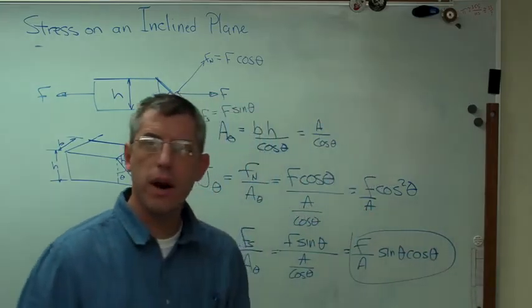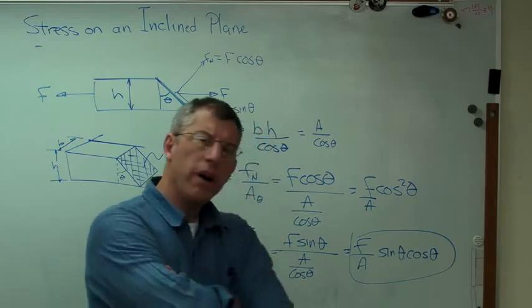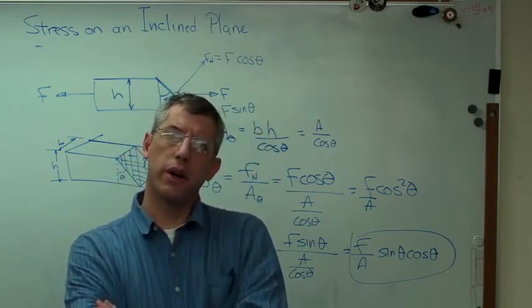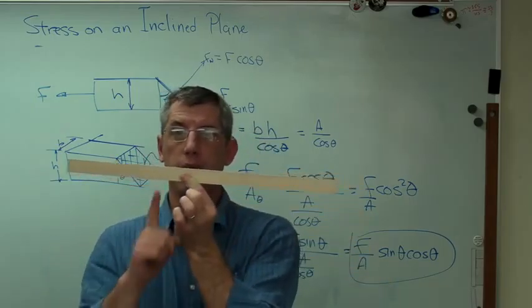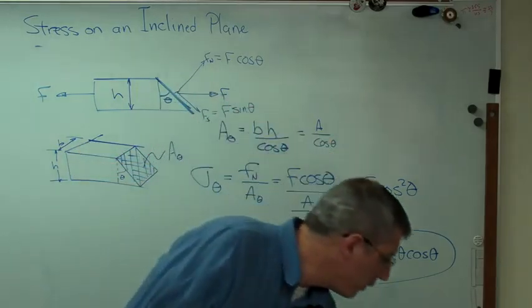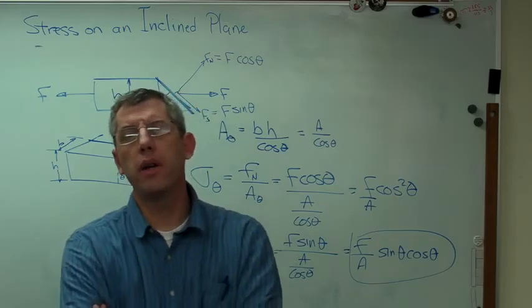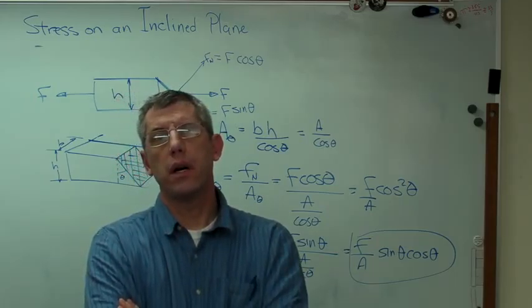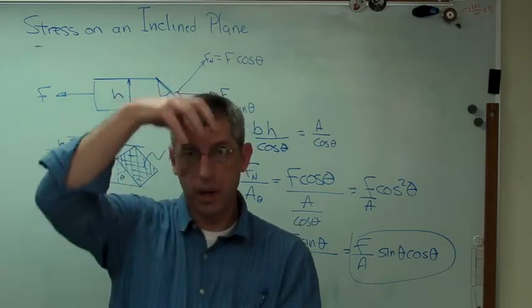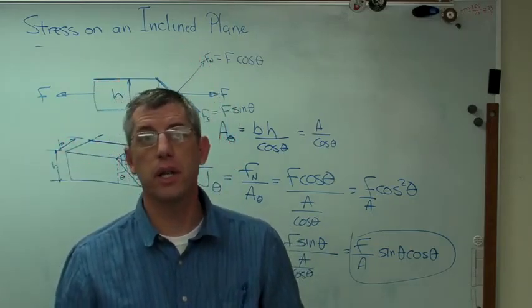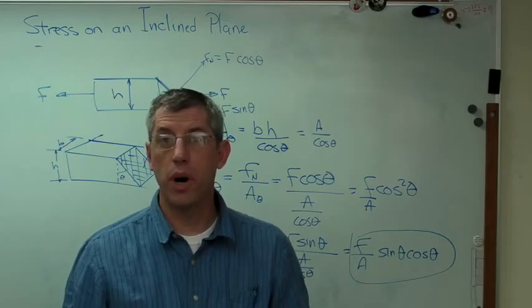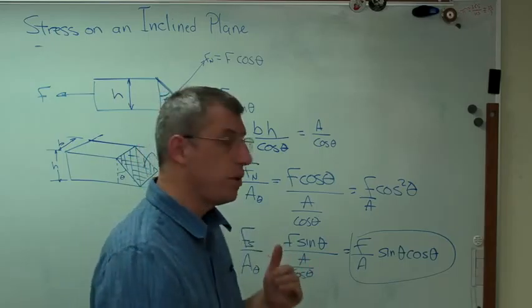What's the maximum there? Now, we already know that stress is directional. It'll change on a part, even on this little simple part, depending on what direction you're looking at. If you look around you, sometimes columns that are nominally under axial force only, either tension or compression, don't break perpendicular to their axis.